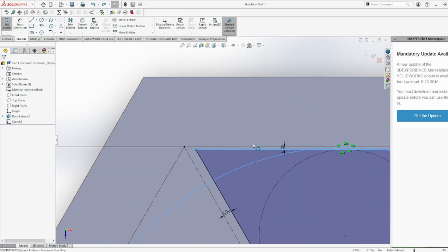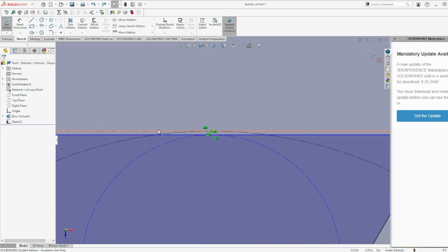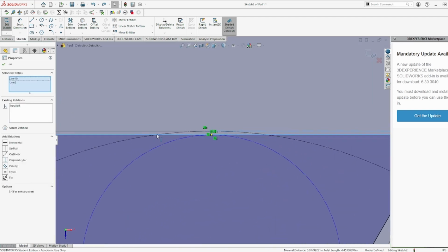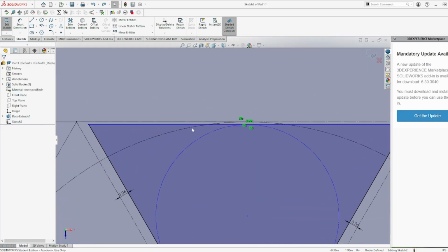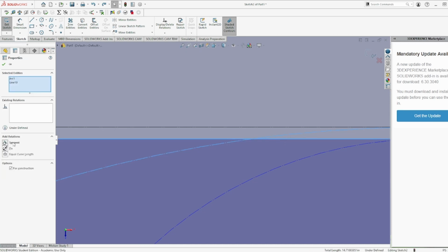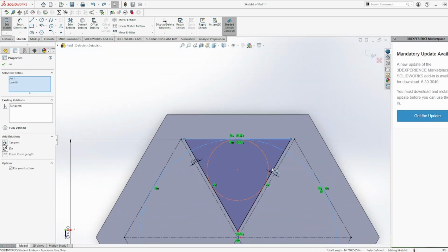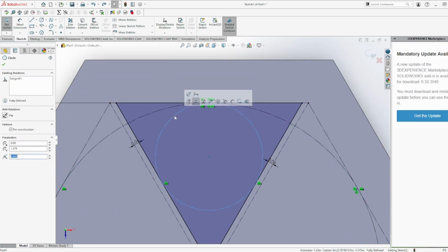I am facing some errors right now, so let me get rid of, okay, that's good. These two are parallel already, we know that. So next I want to change these two to be tangent to each other. Tangent here, yeah, that also forces the back. So either way it works. And now I'm going to delete the circle in the middle because nobody needs to see that.